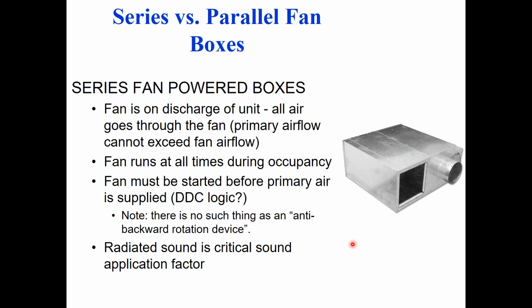This fan is going to run continuously during the occupied hours. So when the building goes occupied in the morning, this fan's going to turn on. When the building goes unoccupied at night, that's when it will turn off. That'll be in stark contrast when we talk about parallel boxes in a minute.